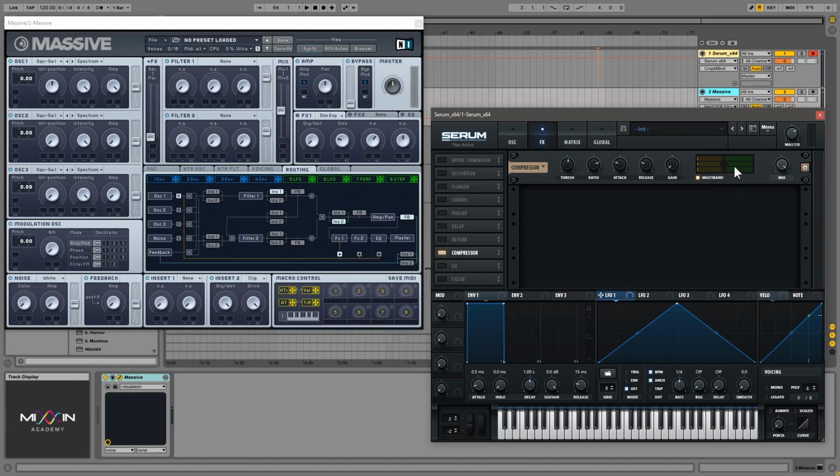Another special thing about this multiband compressor is that it's modeled after a really popular compressor being used today called OTT. This compressor has the downward compression like the normal one I just showed you, separated into bands, but it also has upward compression that serves to actually boost up the signal that is under the threshold. So it will effectively try to keep the signal's balance within this black area right here.